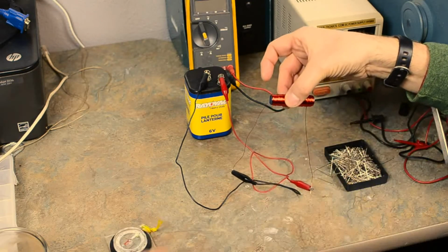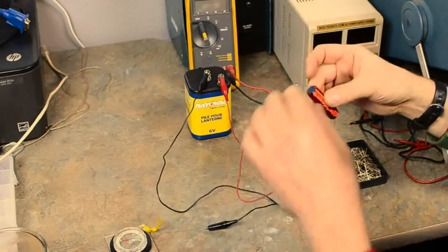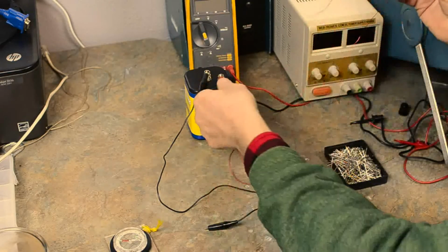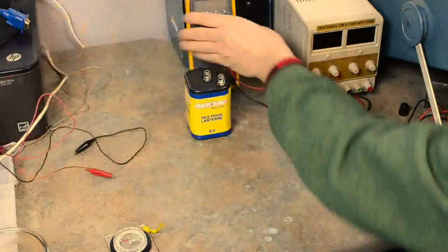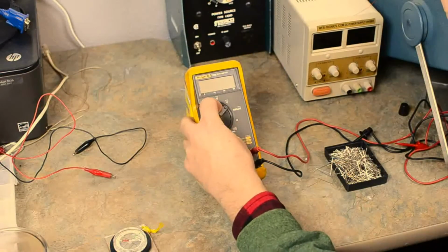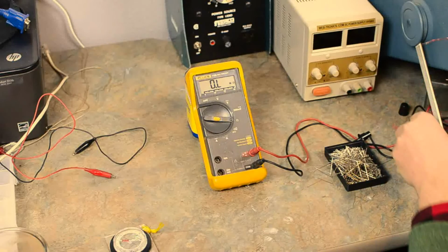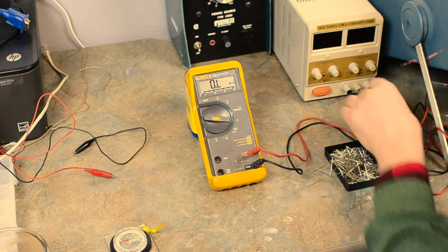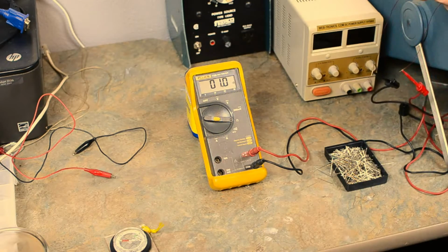electromagnet. I'm going to go ahead and disconnect this because this is getting quite warm. And let's see why this is getting so warm. I'm going to go ahead and disconnect this so we don't short out the battery. Here I have a volt ohm meter, and I'm going to set it up for ohms. And let's ohm out this wire here. See what kind of resistance we have. Okay, we only have 1 ohm of total resistance.